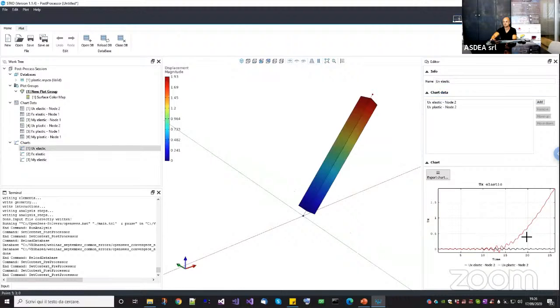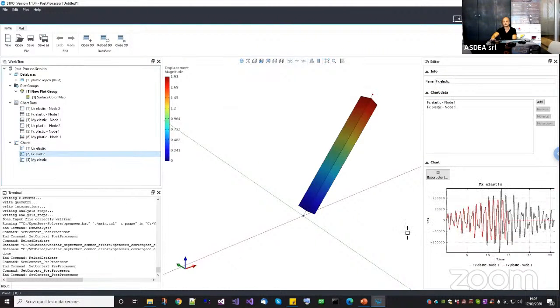So if we look at the displacement here, they're actually not matching the ones in ETABS. If we look at the force, we can see that here we had some convergence problem, and that the bending moments the same. Now, at least the force and the bending moments are related pretty well, okay? So we can see that up to here, we maintained a good equilibrium, but at a certain point, we accepted a wrong solution.